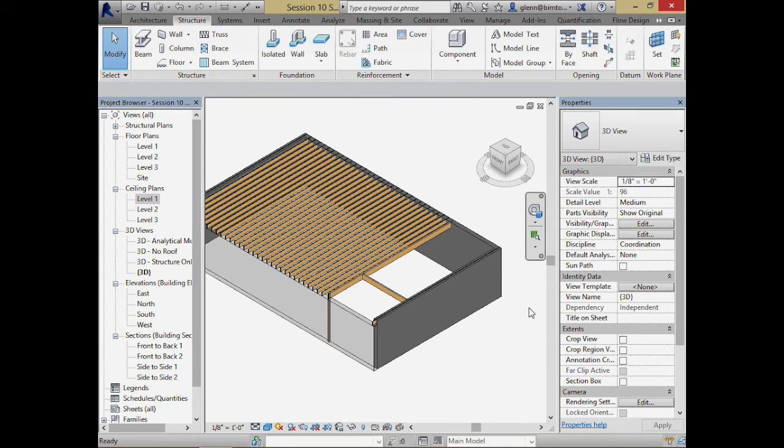Okay, let's say it's 40 pounds per square foot, live load, and they're 16 inches apart. So what I'll do is take 40 times 1.3 times 10, that would be the total load. I divide it in half. Half the loads go into this wall, half the loads go into that wall.